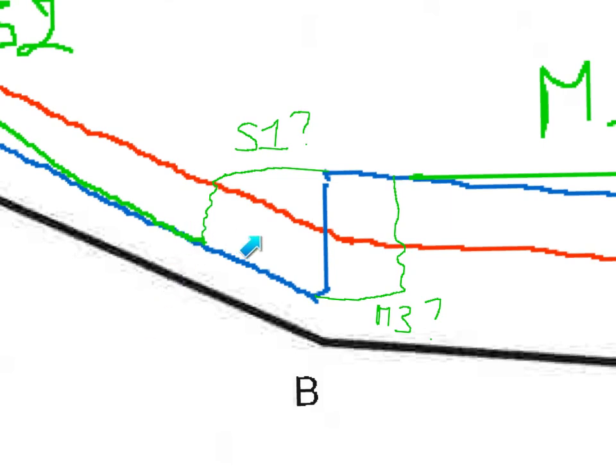So how do we make the decision as to where the jump's going to happen? Well, basically all we have to do is to choose one of these two possibilities and do a little bit of a calculation. If we have a hydraulic jump and we know the depth on one side of the jump, we can use the hydraulic jump equation to find the depth on the other. So, for example, if we assume the jump was here, we know this depth is the normal depth on AB, we can use the jump equation to find the depth just on the other side of the red line.